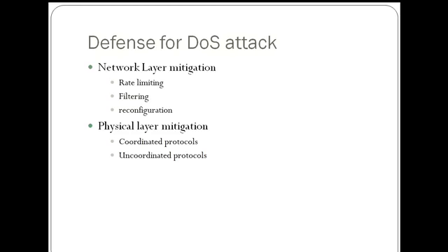When it comes to coordinated protocol, this method has already been applied in the area of wireless communication. There are three schemes: direct sequence spread spectrum, frequency hopping spread spectrum, and shift spread spectrum. However, the secret is supposed to be confidential to attackers, the spreading sequence in DSSS and the hopping pattern in FHSS. This assumption is not correct in an open communication environment. Thus, we could say that this protocol is weak when attackers launch a targeted attack if they have the information of the protocol.